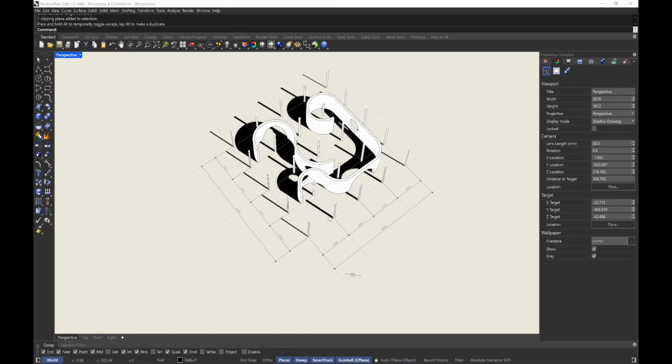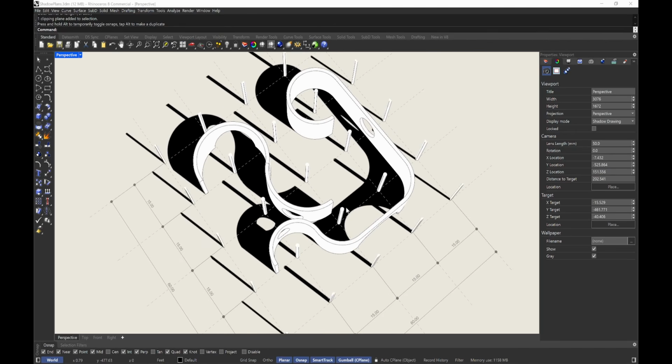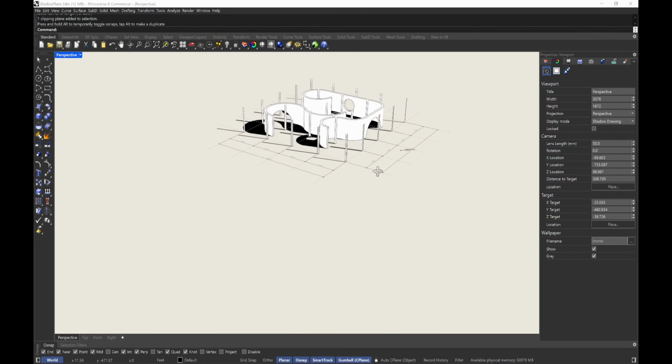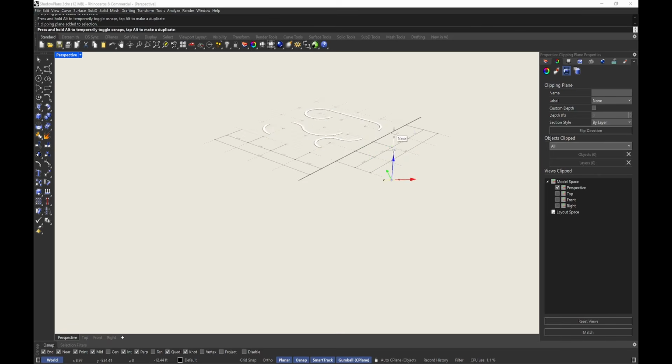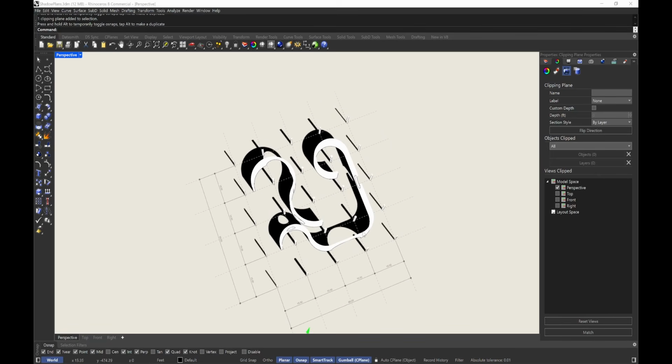That's because in the settings I said ignore clipping plane shadows, which is why you have to have it unchecked. But also you see how the fills here are white, you don't see any outline at all. Even if I drop this lower and cut through the walls, you can't even see the cut of the walls.